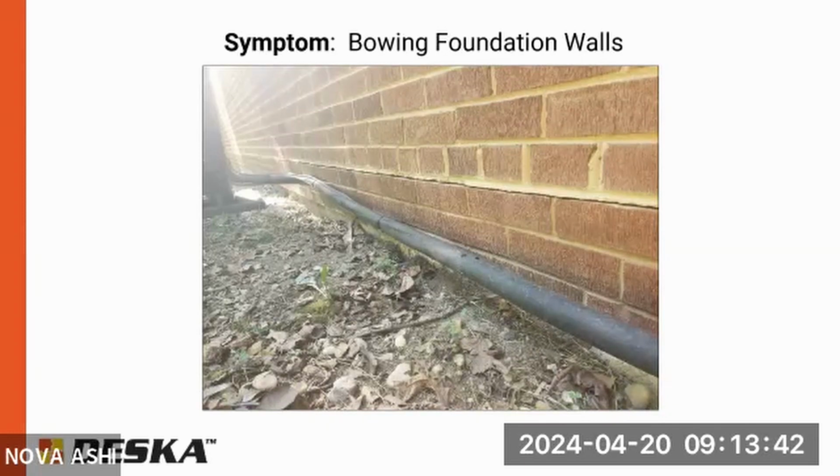This is another example of the same thing, except it's actually on the exterior above the wall. You have the inward hinge of the wall at mid-height, and then this is kind of the opposite, the equal and opposite pivot point of the wall above grade, where it causes, in this case, the brick facade to separate to allow for that movement.